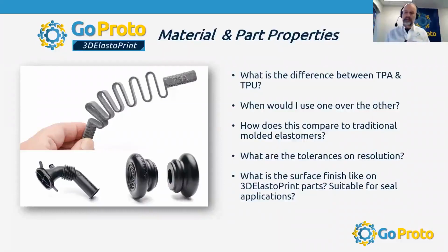A case for elastomer and things that you could use are automotive fasteners and so on, and living hinges are a big thing, and that often gets down into the 20 to 25 thousandths, or like 0.5 millimeter or so. It will print those, but we'll need to look at it carefully and analyze it in the design for manufacturability stage.